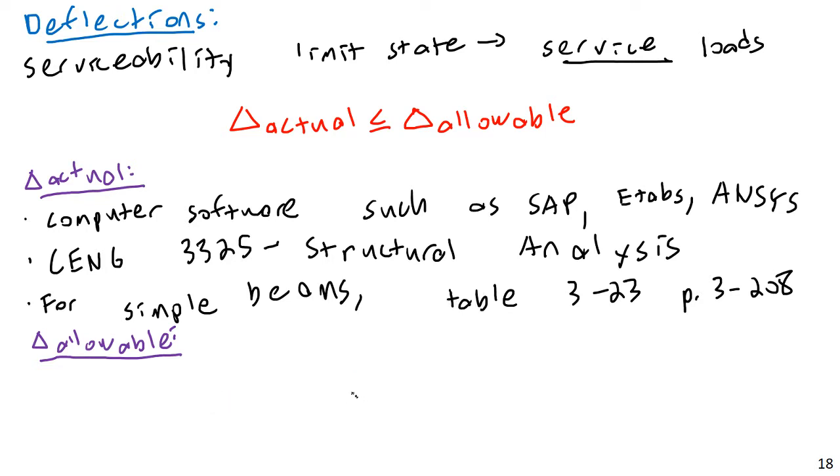So you'll have things like, very common, L over 240, L over 360, etc. And do be very careful to use compatible units on this. It's very common for students in steel design or other undergraduate courses to get maybe a deflection in inches, and then forget to turn the beam length into inches when they divide this out. So watch your units.